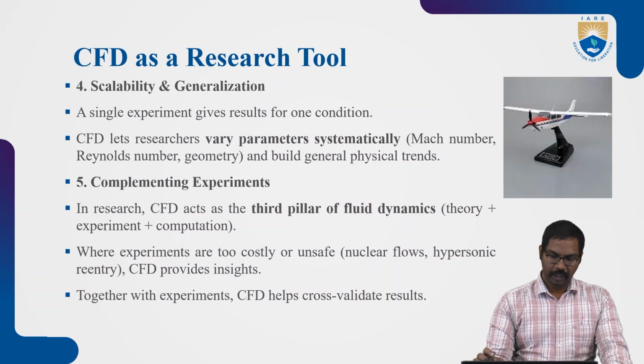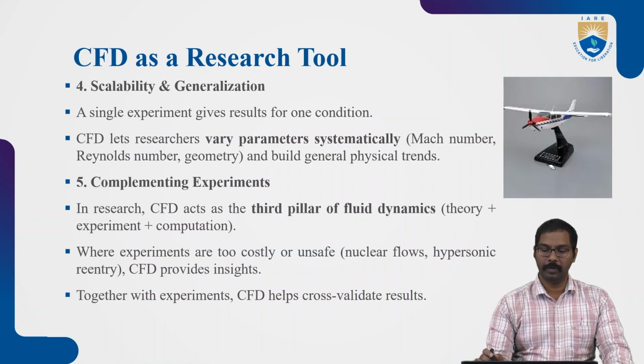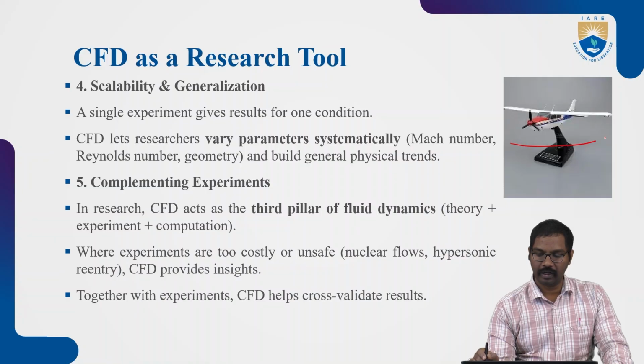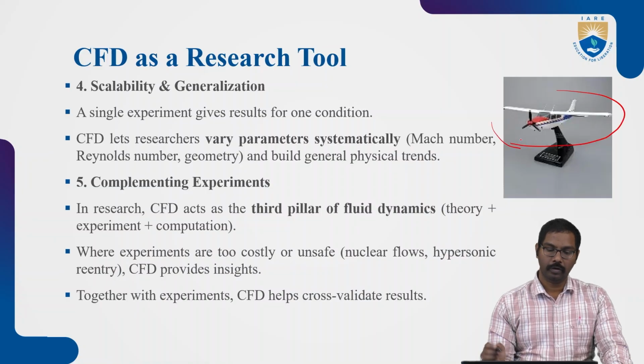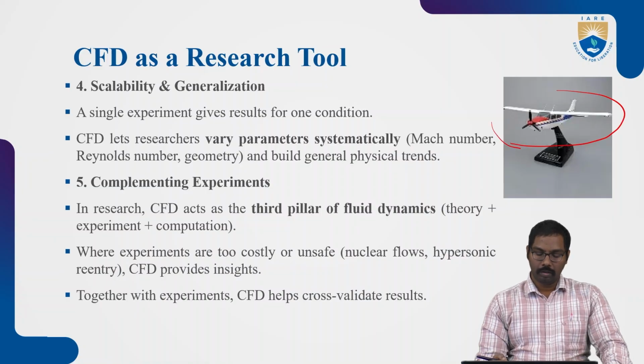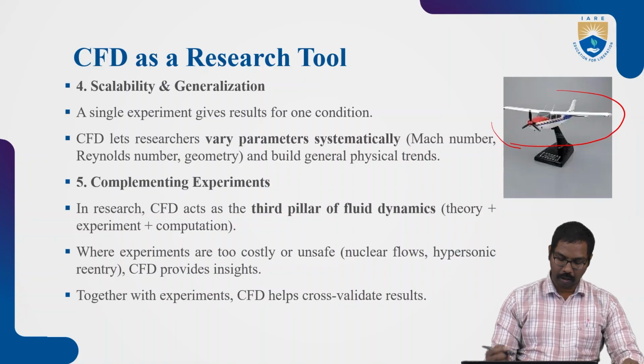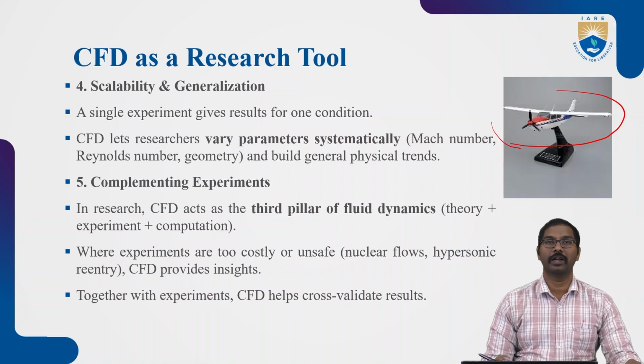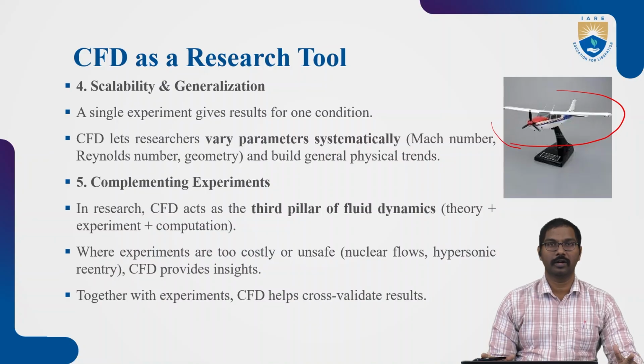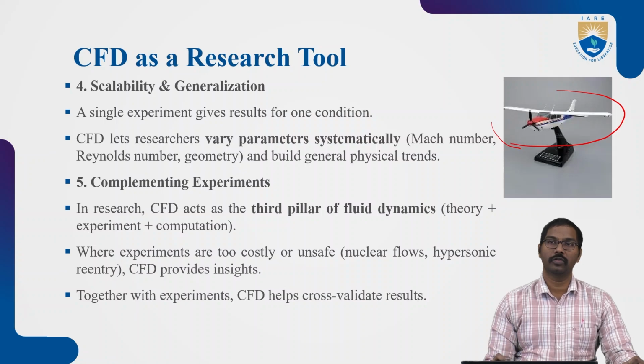Here the initial prototype is going to be developed, and this prototype is going to be solved for different conditions. We cannot make the original model and test it in the wind tunnel. The same size we cannot place in the wind tunnel, because the wind tunnel size is very small compared to the aircraft models or rocket models. So we are going to scale that model.